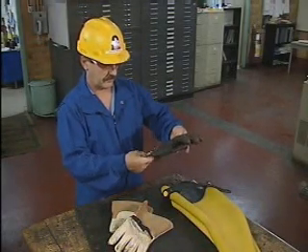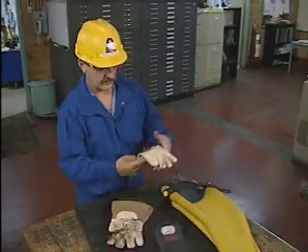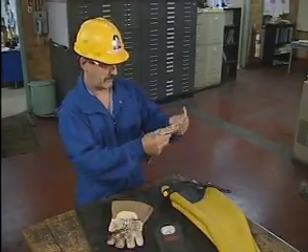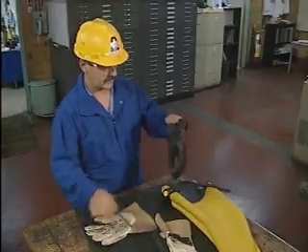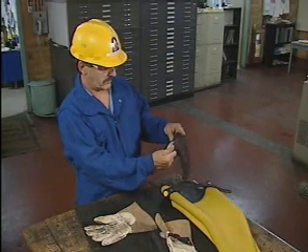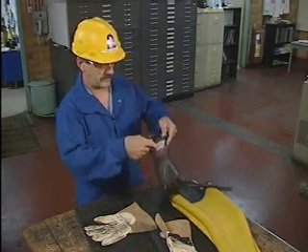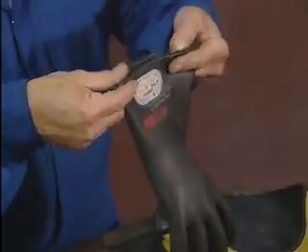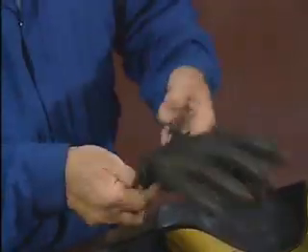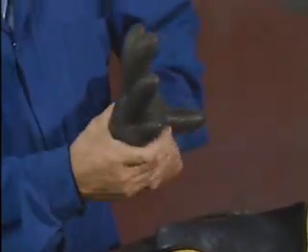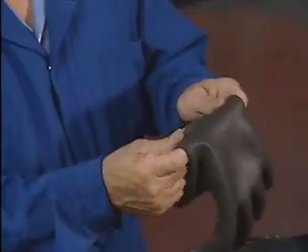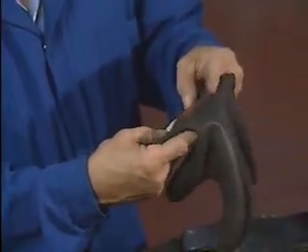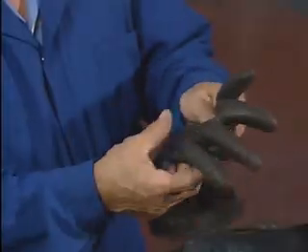Since rubber protective equipment provides insulation from electrical shock, it's essential to inspect the equipment before using it. Rubber gloves should be checked carefully for cracks, worn spots, cuts, and holes. A simple and effective way to check for small punctures is to twirl the glove to trap air inside it, and then gently squeeze the glove to see if it stays inflated. This inspection is extremely important. Even a pinhole leak can be enough to allow current to enter your body.